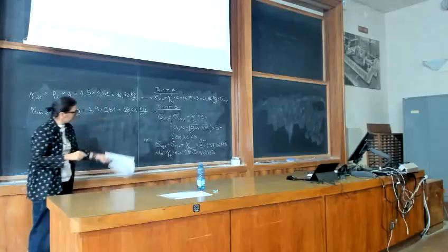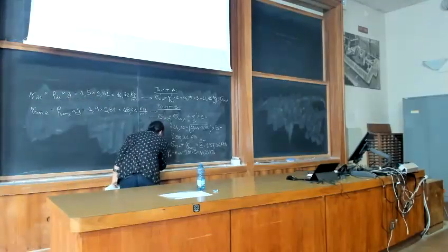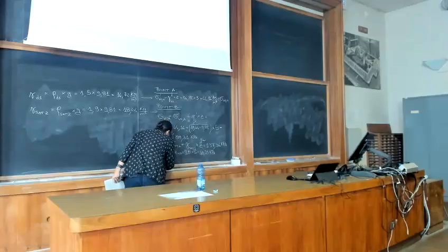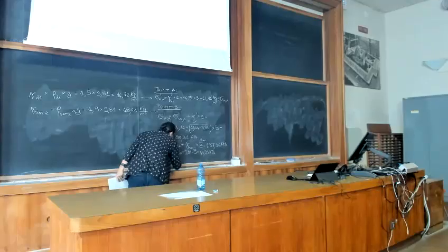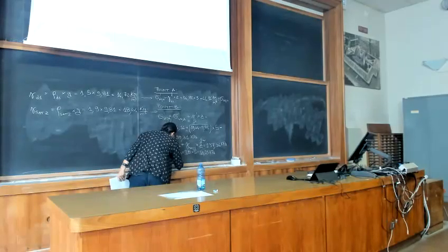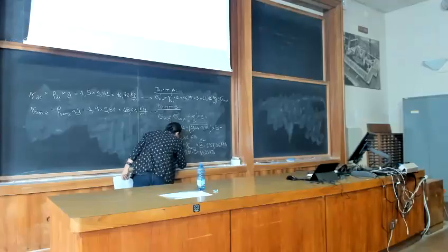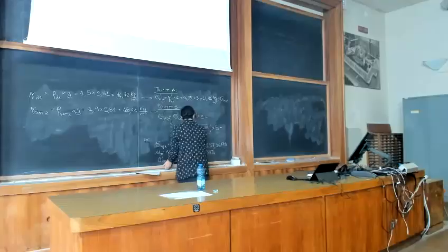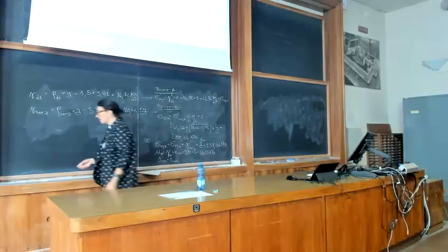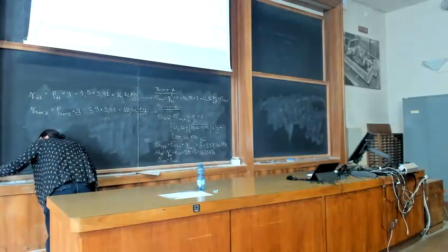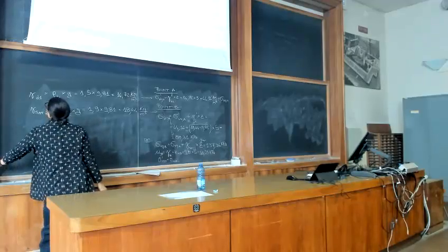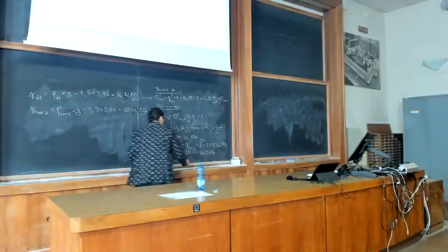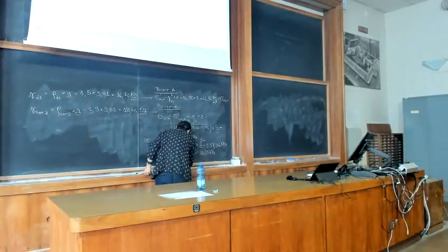And then you could obtain the same result you have above, so sigma dash V naught in point B is sigma V naught in point B minus U naught in point B. Okay?